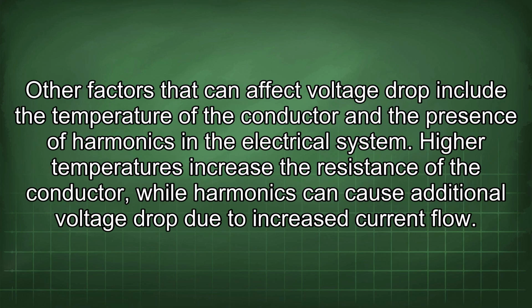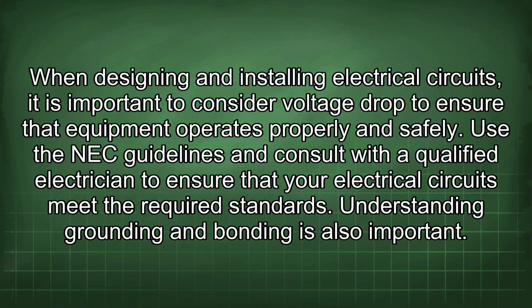Other factors that can affect voltage drop include the temperature of the conductor and the presence of harmonics in the electrical system. High temperatures increase the resistance of the conductor, while harmonics can cause additional voltage drop due to increased current flow. When designing and installing electrical circuits, it is important to consider voltage drop to ensure that equipment operates properly and safely.